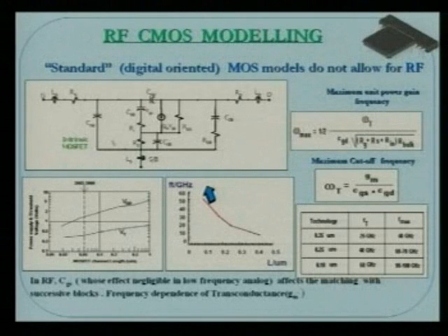VGS is the voltage across the capacitance CGS, then the drain to source resistance in parallel to that current source, and then there will be C drain to bulk, and then there will be the drain resistance and the inductor, because in the transmission line model each of the resistances actually has an inductor and a resistance.